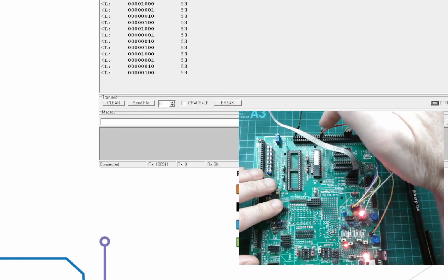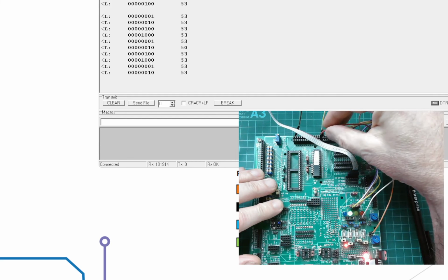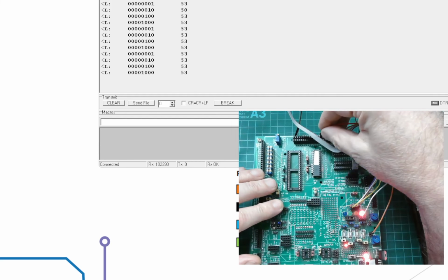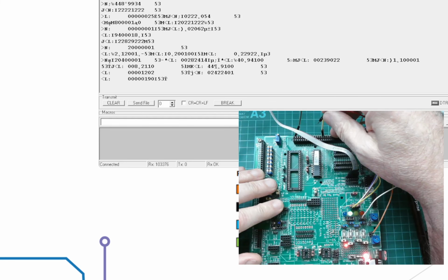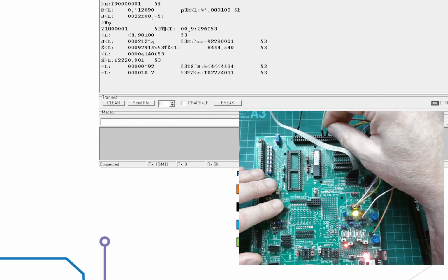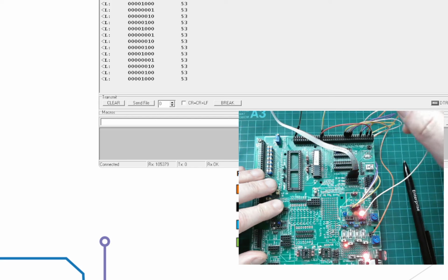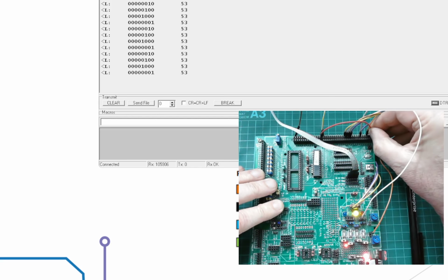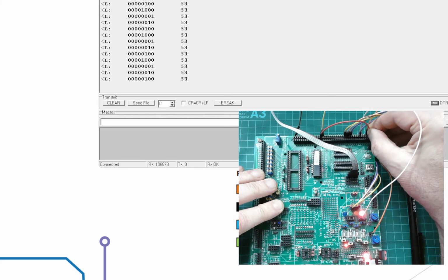Up the top here, I told you earlier on, there's a voltage domain. This is the voltage domain. This is on C.7, or equivalent to what used to be called C.7. If I unplug that, trust me, that's not GCBASIC. That is the voltage domain being incorrect. Put the voltage domain back in. I will change that voltage domain from 5.0 to 3.3. I can easily do that on my board, and it comes back up.